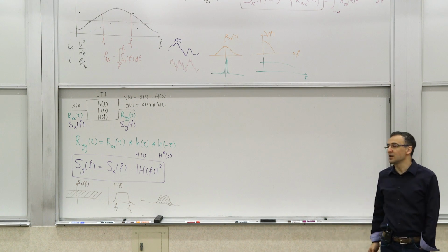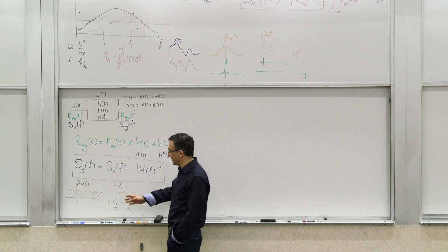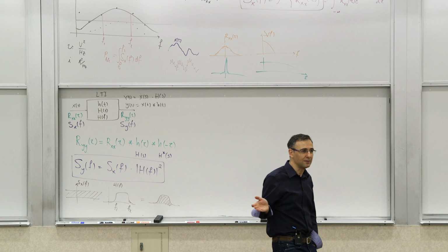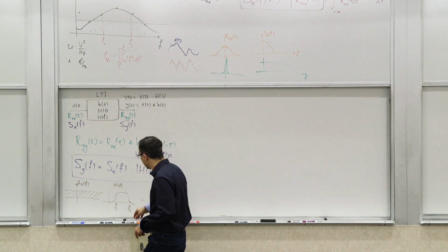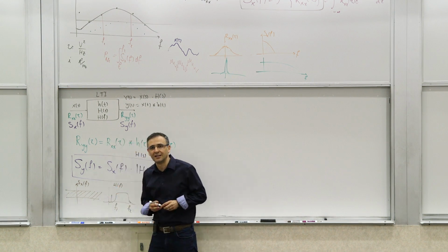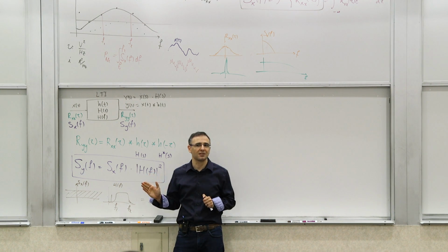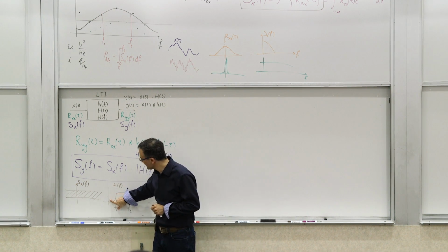And you may say, why would I do that? Well, sometimes the good thing about noise is that, especially if it's something like white noise or broadband noise, it's everywhere. So if there is, for example, some parasitic resonance response, let's say there is some peaking here, you may not see it if it's very narrow band on a sweep, but the noise will make it come out. So you will see it everywhere.